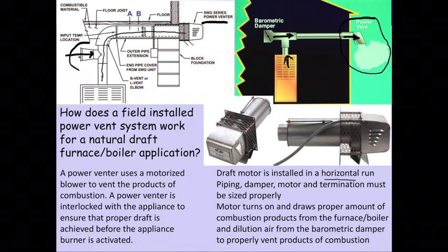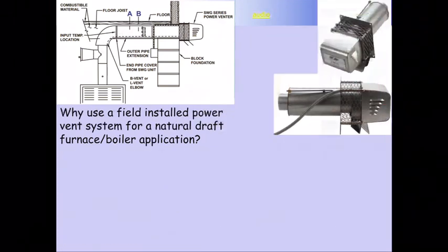The power venter will ensure that you will have draft in the undersized system if they size it correctly. But again, you really have to engineer these correctly. And then of course, the motor turns on, we make the amount of necessary draft, we draw dilution air, and we get things to work right. So it's a pretty neat little system.